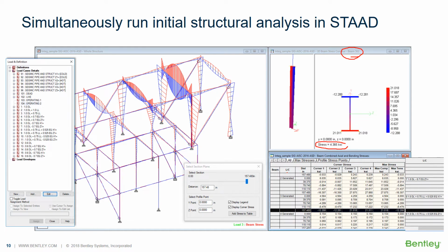At this point, what we're looking at in our results down here for our corner stress and maximum stresses is these equations, 7, 8, and 9, which is basically just reviewing the structure combinations only including structure, and they're just some combinations that are including dead loads, live loads, and operating loads.